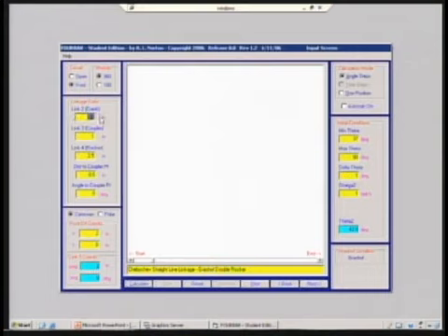type the dimensions of the links, and I'm going to go back to my paper here, and read the numbers off of my previous work. We decided that the crank wanted to be 2.5, which just by happenstance it already is. That wasn't planned. The coupler we decided wanted to be 3.75. I'm tabbing between these boxes. The rocker wanted to be 6.25, I think we said. The distance to the coupler point we said was 6.2. And the angle to the coupler point was 21.32 degrees.